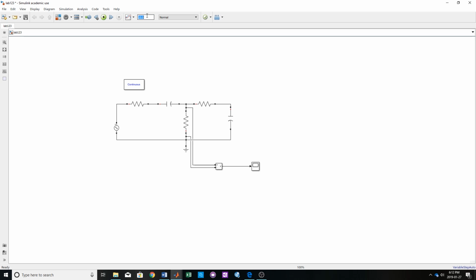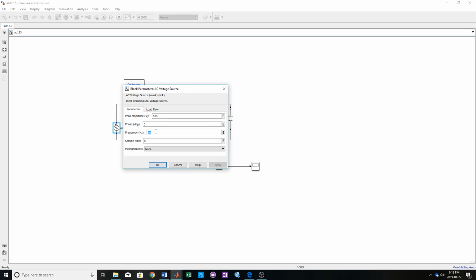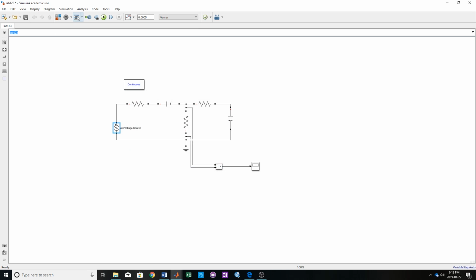I think you can do really small numbers, so I'll do 0.0005 seconds, something like that. And then frequency here I'm going to set to 20,000 hertz. Okay, and then you're going to have amplitude set to 2 volts peak, not peak to peak, just 2 volts. Okay, and once you're done with everything in the circuit and it looks good, you connect it like this, right? You have the measurement device, and it goes into the scope.